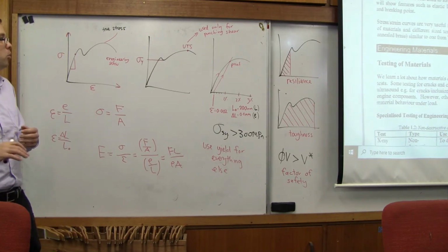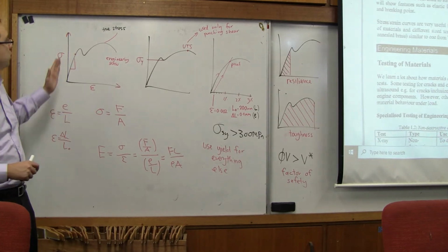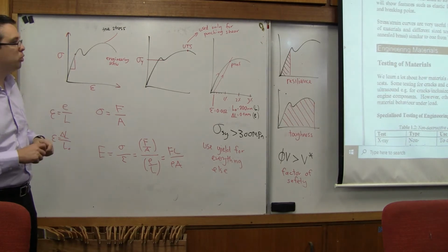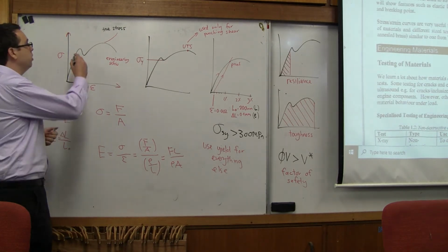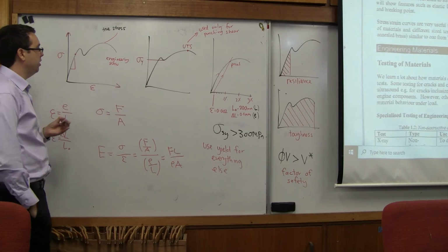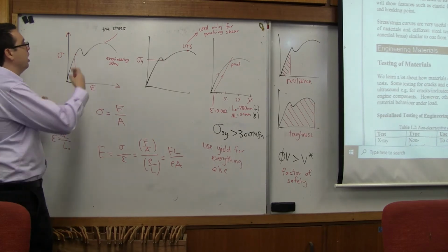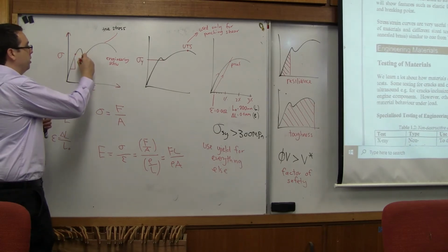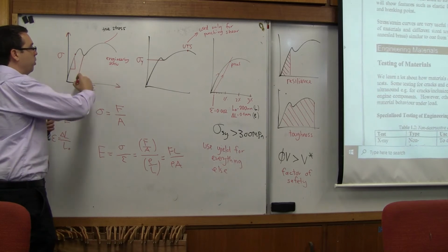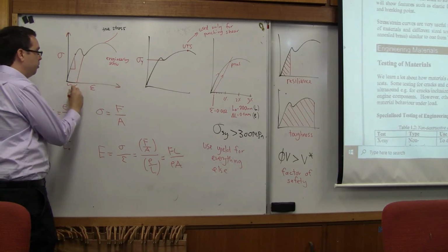I may have spoken a little bit more about it in Year 11, but the idea is that the residual stresses will remain. If we load to this point in the graph and then release the load, it's going to come back here, and that becomes our permanent deformation.